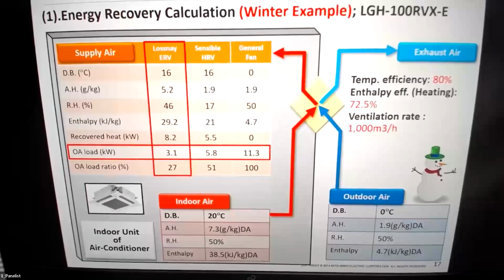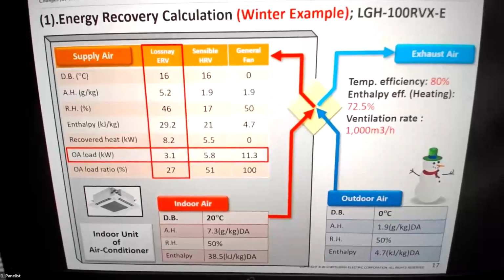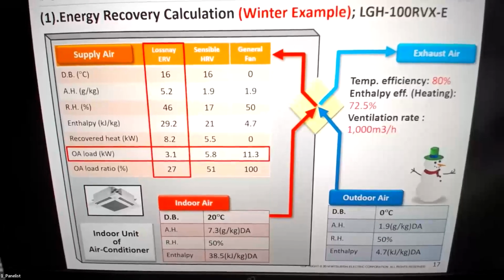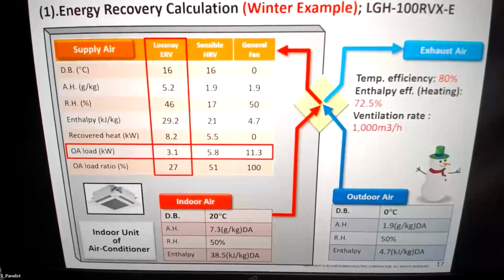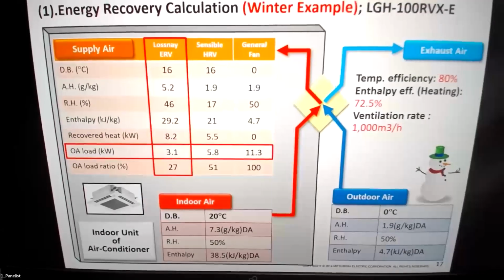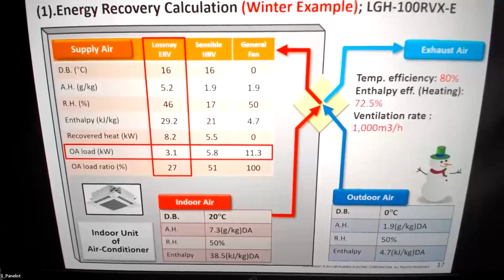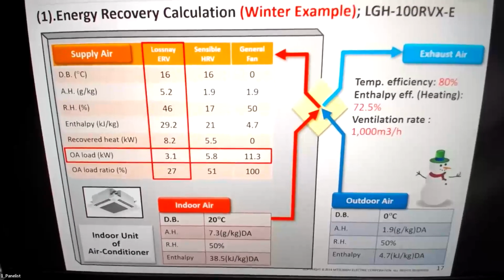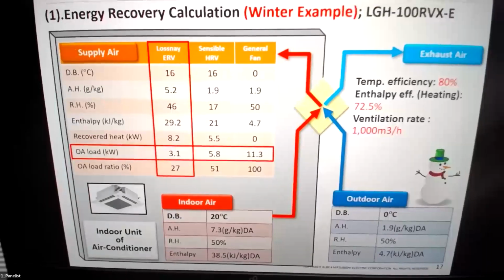And if very cold climate, -15 or -20, like Russia or Northern European countries, even America, we recommend to equip a duct heater, like an electric heater, before taking the outdoor air to the unit for protection. So it's not energy saving against the energy saving issue, but we need to take a balance between, how to say, product protection and cold climate operation.